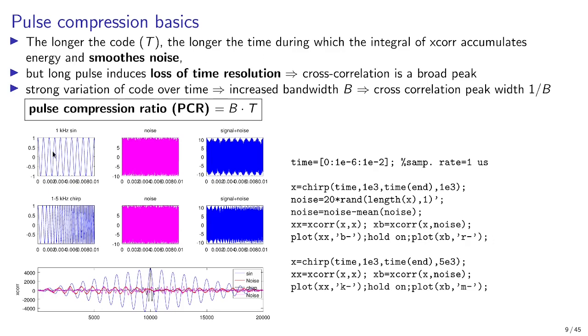The objective is hence, rather than having a uniform window, to have some sort of structure so that the correlation of the beginning of the window does not correlate with the end of the window. As an example, a chirp will allow such a result because the beginning of the sine wave is not the same as the end, a chirp being a varying frequency, sine-shaped signal.